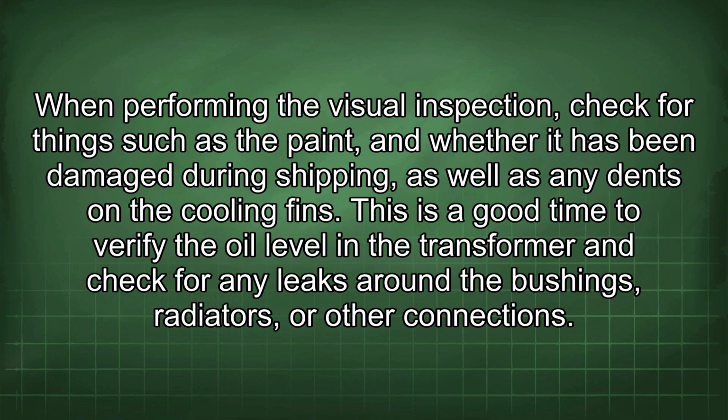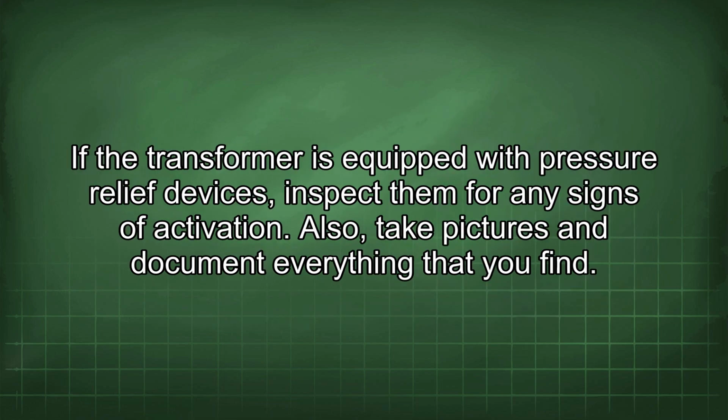This is a good time to verify the oil level in the transformer and check for any leaks around the bushings, radiators, or other connections. If the transformer is equipped with pressure relief devices, inspect them for any signs of activation. Also, take pictures and document everything that you find.